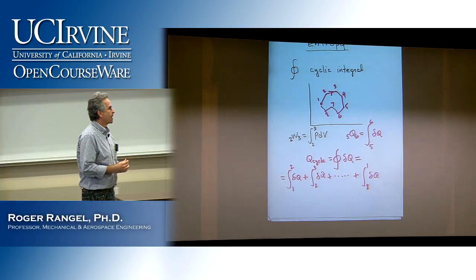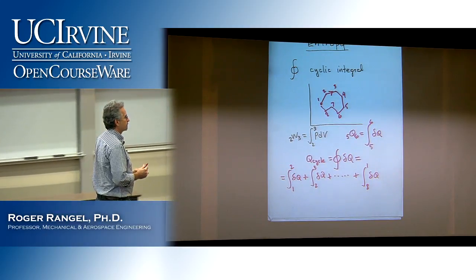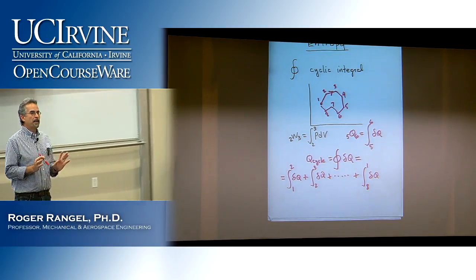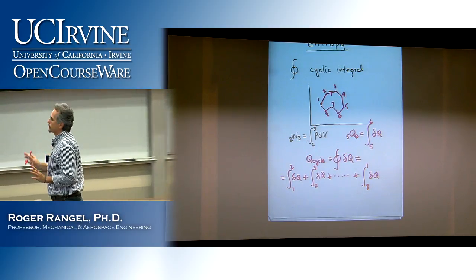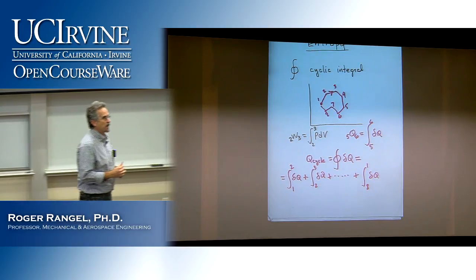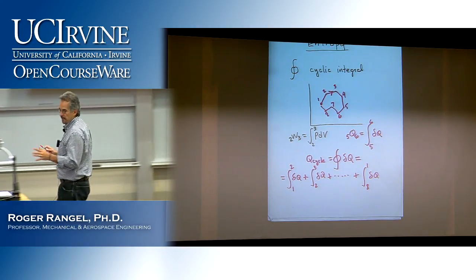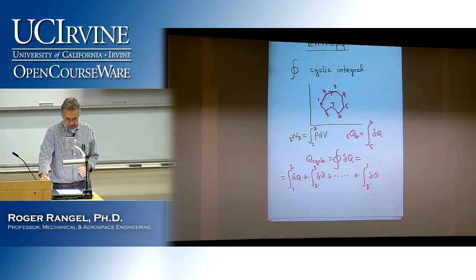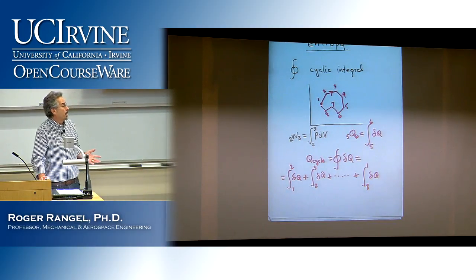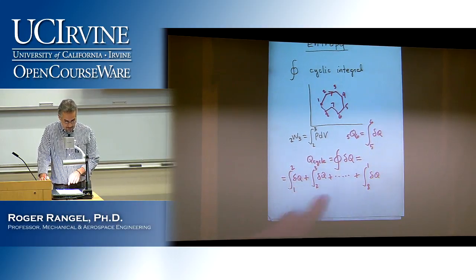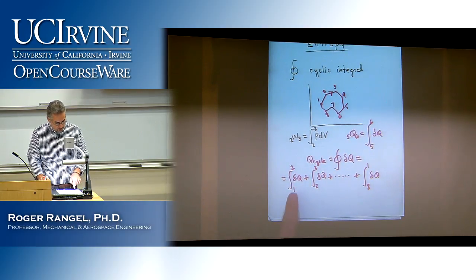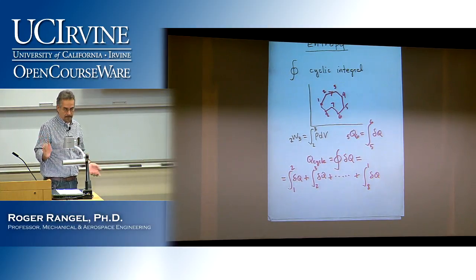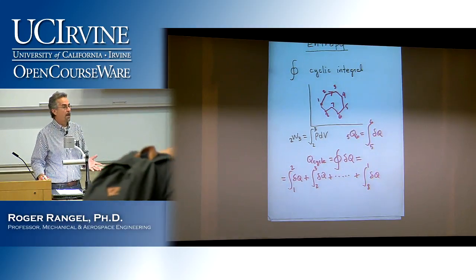Yes, sir? Does this imply that cyclic integrals apply to reversible processes? No, I haven't made any distinction. This is any process, right? Any process. We haven't really said whether this process or this cycle as a whole is reversible or not. I'm just doing a calculation of the heat transfer. For example, if I do this, I'm adding up all of the heat transfer contributions for each of the sub-processes, so I get the total, the net heat transfer for the cycle, and I could do the same thing for the work.